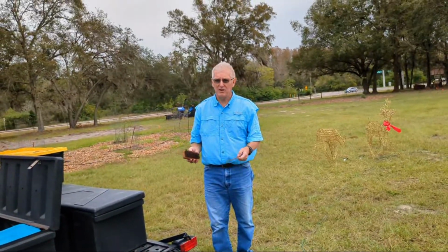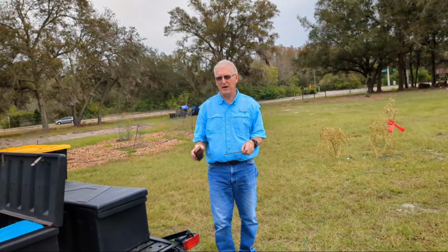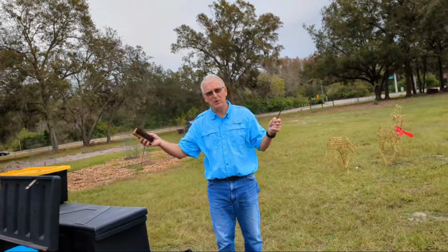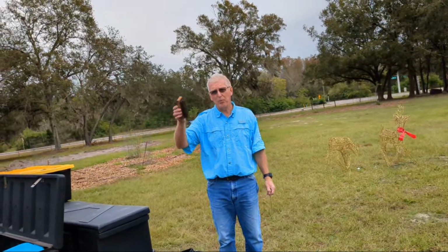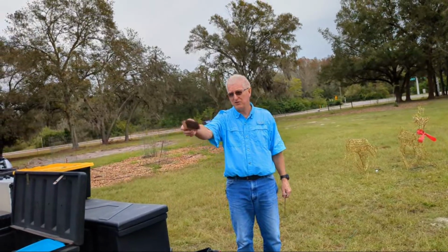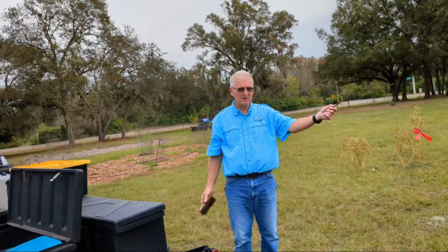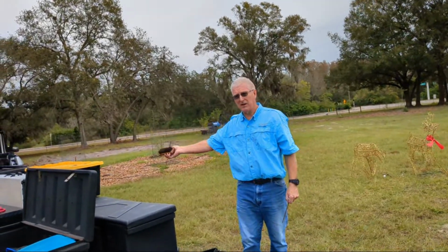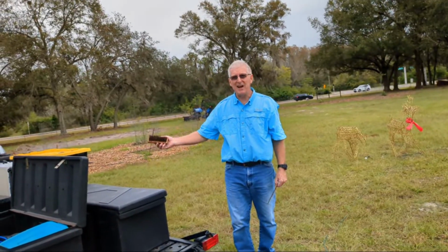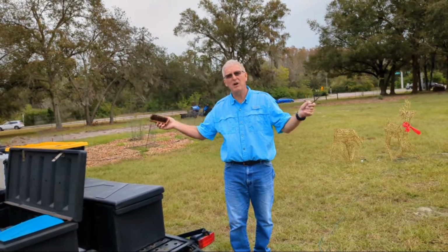And that's only for 240 volt systems, right? It would only be if you're not connected to the grid, because you violated the rule again unless you open that bond, and you'd have to do that physically by unscrewing something in the generator. So then you'd have a bond in the house, a bond in your electrical panel in the home, and a bond in the generator. And now you've created another problem. Okay? So we wouldn't want to do that.